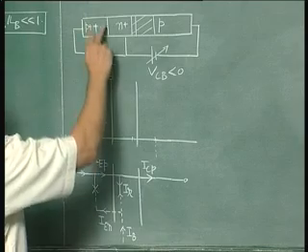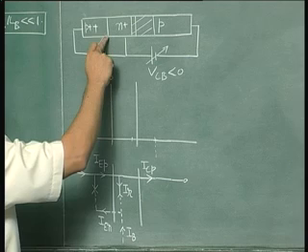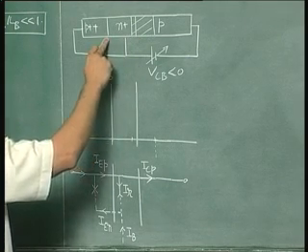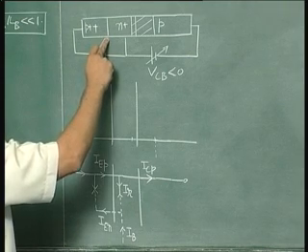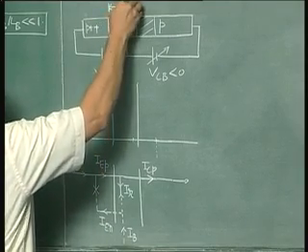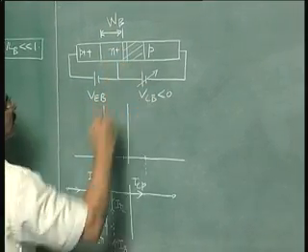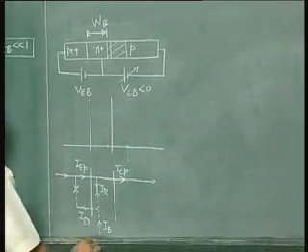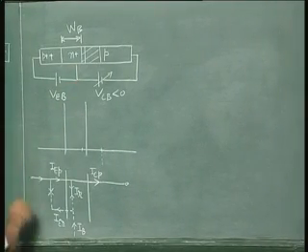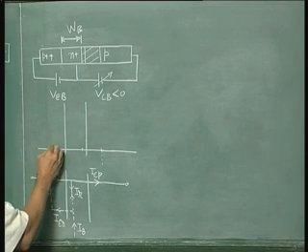Now for simplicity we have not shown the emitter base depletion region, which is also there, okay, but this depletion region will be more significant compared to this, obviously, because this is reverse bias and it can go on increasing, whereas your forward bias cannot change very much, okay. So your depletion region here will not change much, that is why it is not shown. So the base width, electrical base width, which is this, will go on changing as you change your reverse bias. So that is one of the effects, but then we have to see whether it affects the transistor action. So let us plot the excess carrier concentration for collector base reverse bias. This will be as follows.